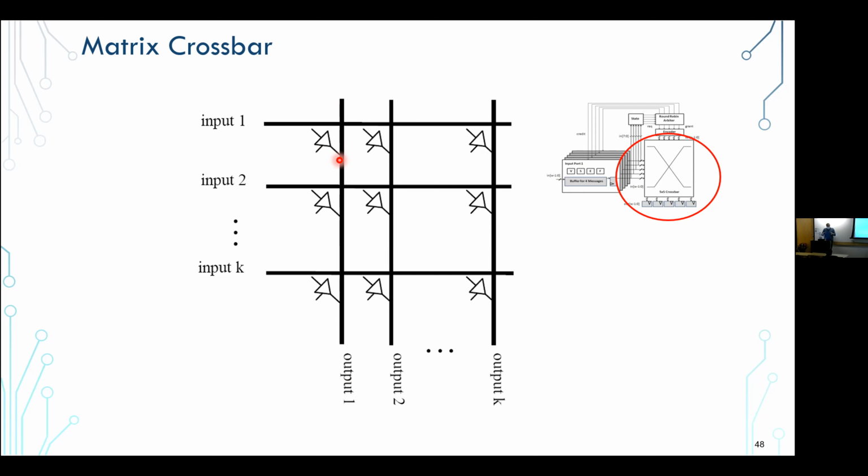And you can't route it that compactly because you're introducing these pockets in the whole grid of the routes of the wires, right? And if you want the tool to do it, it becomes an even bigger mess because the tool doesn't really understand tri-states and what to do with them. So people have done these custom slices.